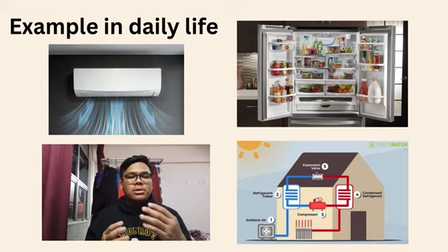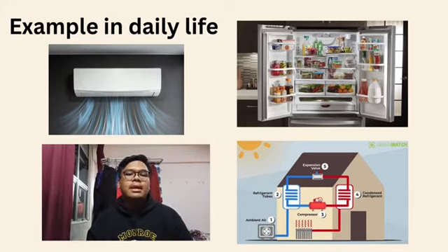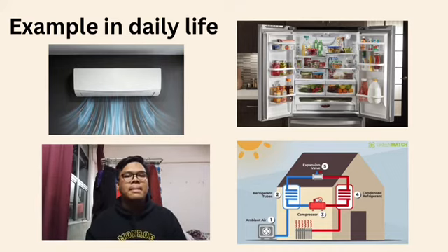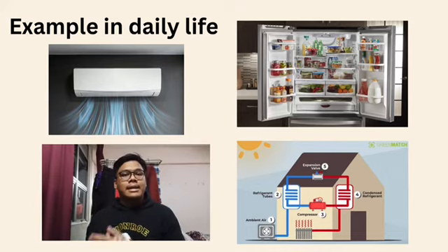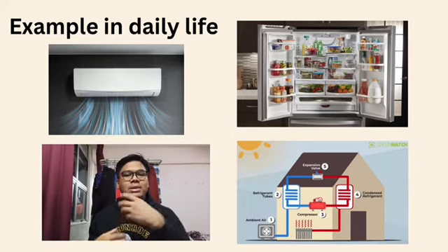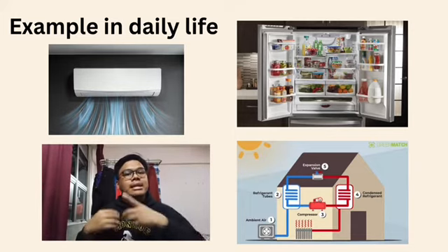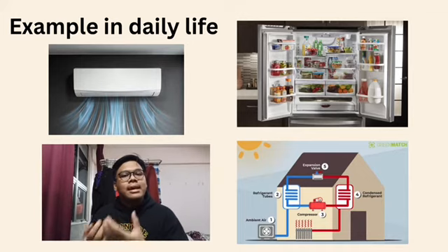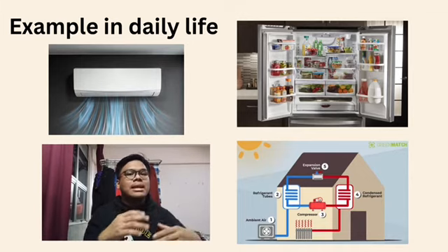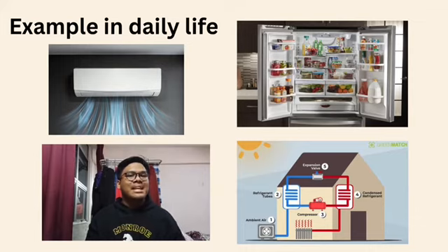Instead of producing cold, air conditioners take away heat. The working fluid is moved outside, where it is compressed and heated by a mechanical pump. The heat is then frequently transported to the outside environment using an air-cooled heat exchanger. It is then transported indoors, where it can expand and cool before absorbing heat from the interior air via a different heat exchanger.